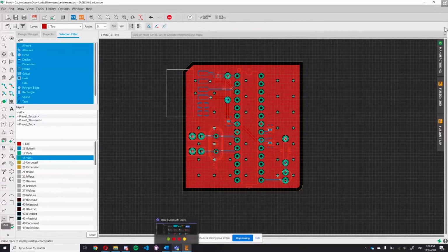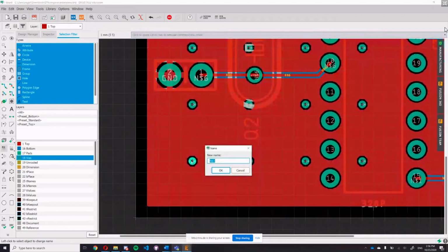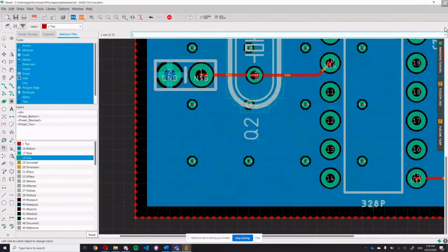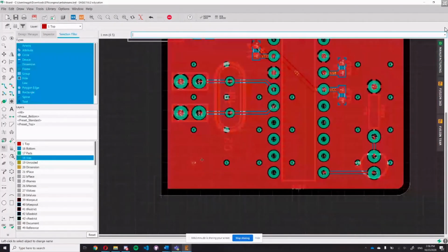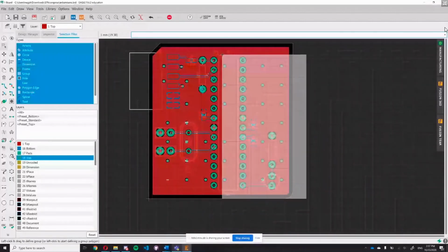Good. So we have the vias, and the most straightforward way to connect the via somewhere is to just rename it. So we click here and we type in GND. We also copy that, and it just connects to both sides. But doing this for each of these would be really hard. So we can use this trick.